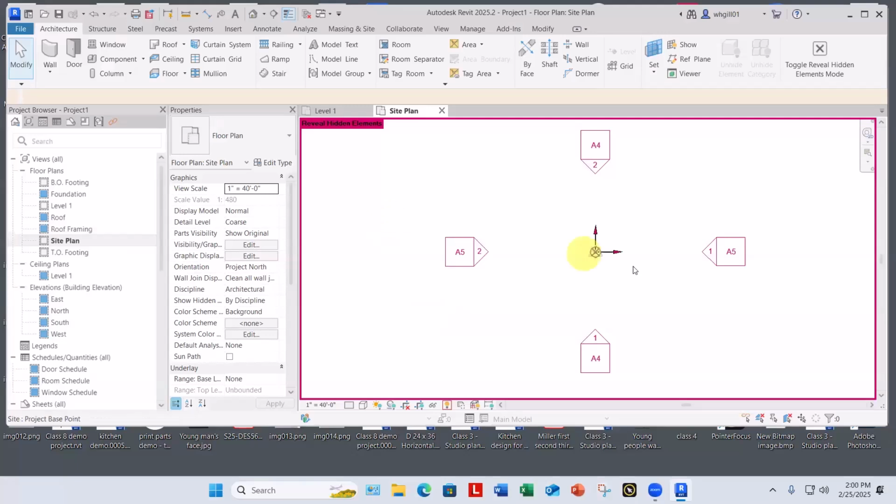But you can see right here, there are 2 objects that are usually right on top of each other. The little X is the project base point, and that's really what we're going to be lining our AutoCAD drawing up with. The other one, which we're never going to deal with, sets how the building is oriented towards true north. Our building happens to have true north straight up. But if it were angled a little bit, we would play with this one. We see it this way, but when it gets down to a site plan, it might be rotated some. So ignore it. Interior designers have no use for that at all. So that's the point we're aiming for, the project origin, right down there. So we can close that back out